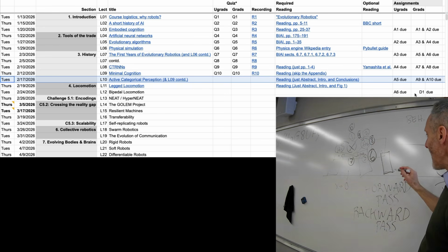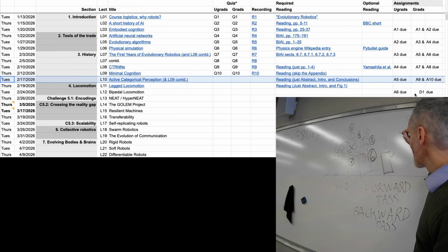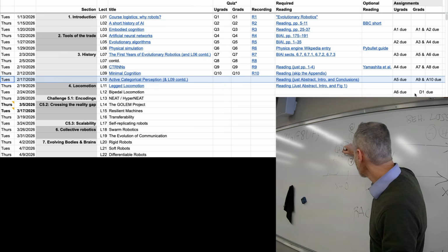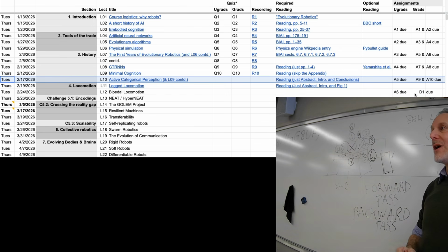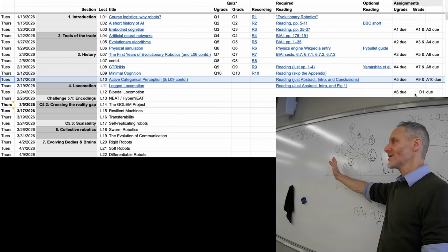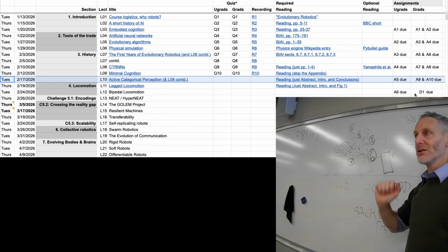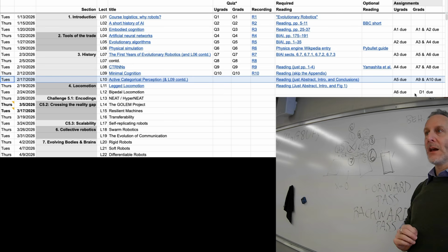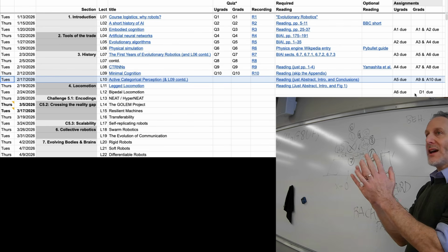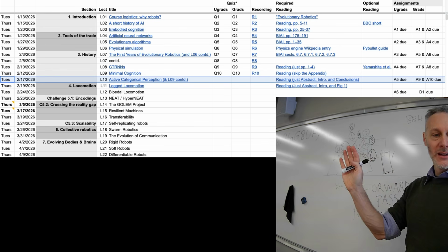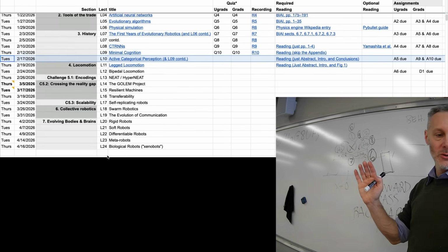So the backward pass, when you do the differentiable assignments, you can set it up so that it also makes changes to the body, not just the brain. It can non-randomly optimize or improve the physical structure of the robot along with the synaptic weights, and guarantee you that the next time you do the forward pass, the robot's going to travel further to the right. Okay, that's a crash course on combining gradient descent and robotics. If you didn't follow all of that, it's okay. We'll come back to it in lecture 22.